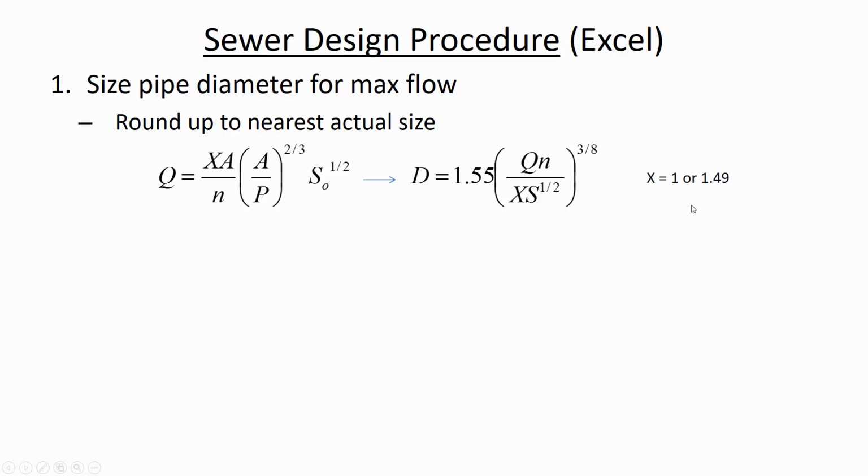So you know some given flow rate. The flow rate is given Q, and you're trying to find out how big should the pipe be. And by the way, these units will be either in meters or in feet. So let's say that you find that the pipe needs to be 11 inches in diameter. Well, there aren't 11-inch diameter pipes available for purchase. And so you'd have to size up and buy the 12-inch diameter pipe.